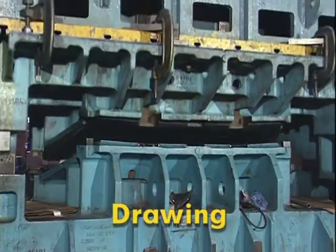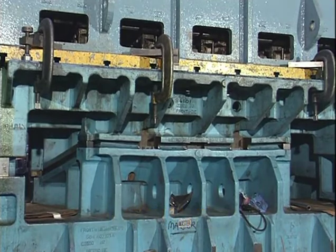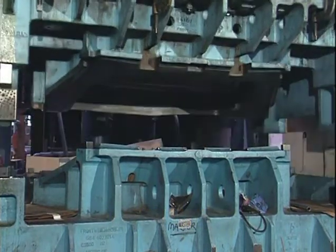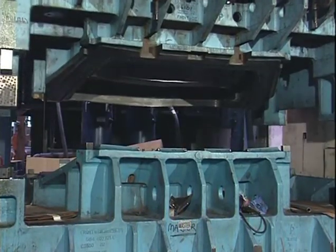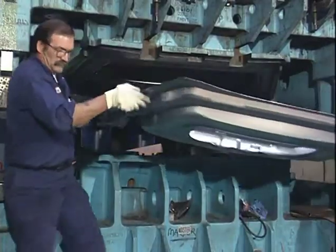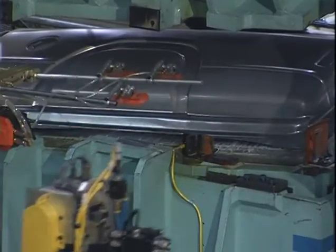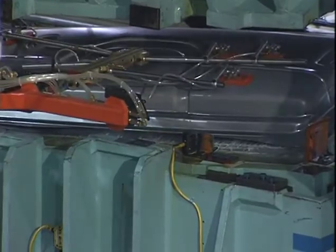Drawing shapes a flat pre-cut metal blank by forcing it into a die cavity with a punch without excessive wrinkling, thinning, or fracturing of the metal. Various complex forms may be produced by drawing. Drawn parts may vary in size from small parts up to aircraft and automotive parts large enough to require mechanical handling equipment.